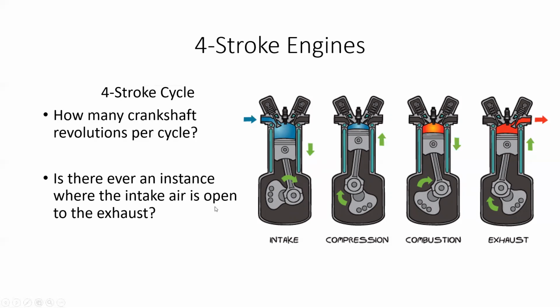All right, so that's your basic four-stroke engine. Looking at this diagram, we're talking about our piston moving up and down in our cylinder, our crankshaft and connecting rod right here, and then our block is this housing where all of this is. Up here would be what's called the head, and that's where all your valves are, which we'll talk about later on in different lectures. But our block is this housing, with the crankshaft, connecting rod, and piston right here. So that's our basic four-stroke engine.